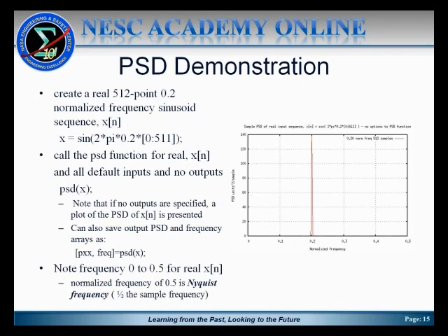And then you can plot that out manually or have it plotted automatically. And what you'll notice, if you let it auto-scale, is the frequency range will be 0 to 0.5. So the only data points will be between 0 and 0.5 normalized frequency. Again, the 0.5 refers to 1/2 the sample frequency, otherwise known as the Nyquist frequency.